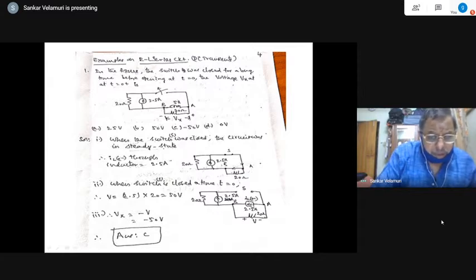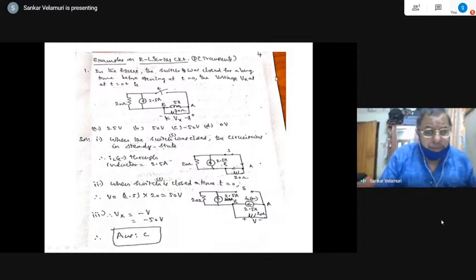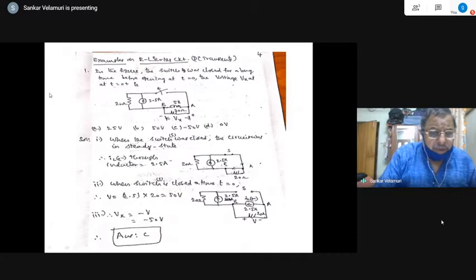So this is I equal to 2.5 now, and the switch is in the other position. Okay, this steady state current is obtained in case 1. The other one is when the switch is closed at time t equal to 0. Now this is the equivalent circuit. You can see under steady state condition, inductance acts as an open circuit. Now you can see the inductor current is flowing through this, right, with the polarity, and the directional current is like this. Okay, this is the corresponding one.